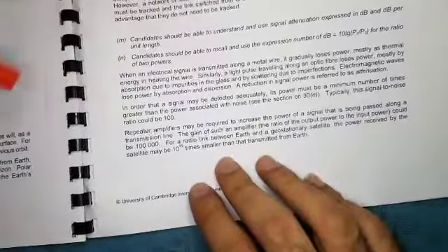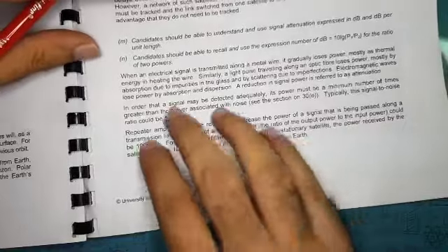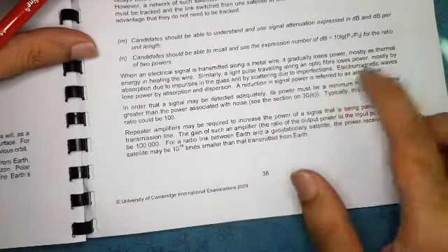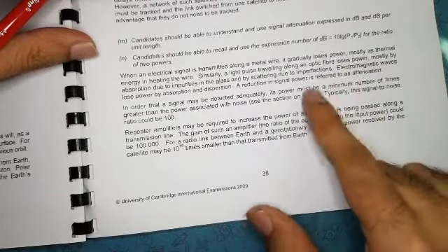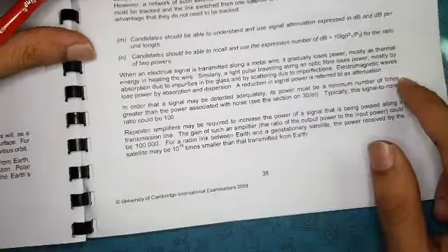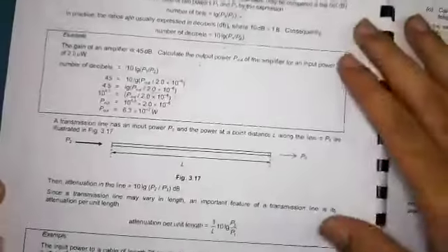So what do we do in that case? We no longer use linear scales. We actually use logarithmic scales. The reason we use logarithmic scales is a two-fold advantage. One, it's easier to represent the data, right? The ratios would be easier to represent using decibels. And the second advantage is if the cable increases in length, instead of multiplying values, you just add the logarithmic values, which makes the maths much easier to work with.